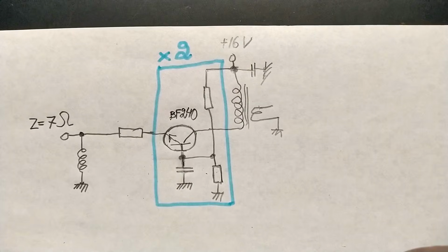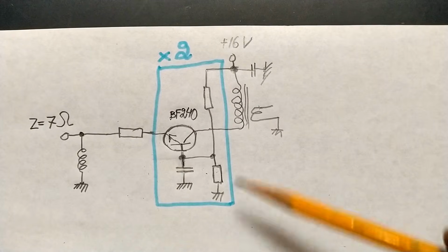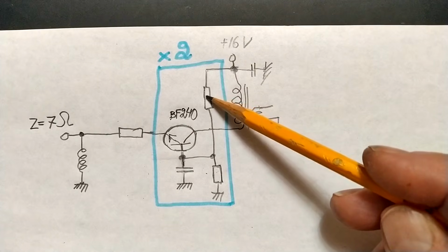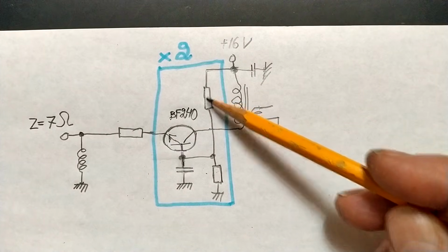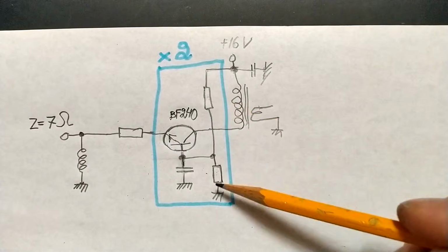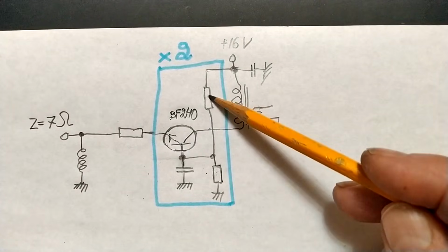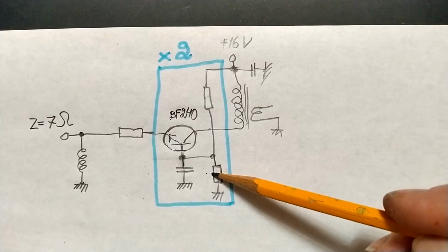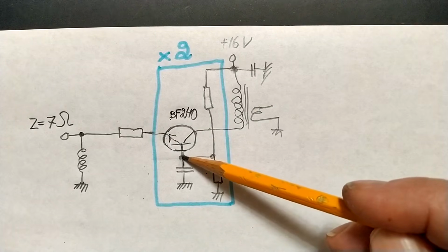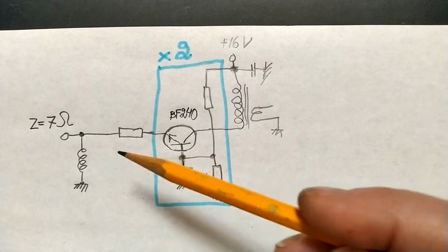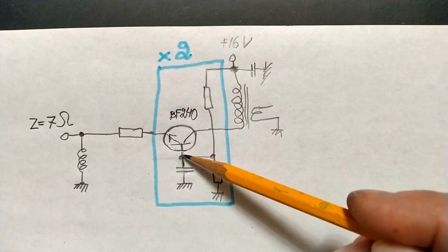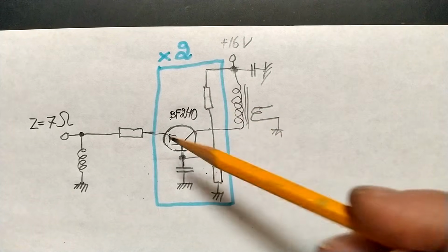This is the current amplifier, two BF240 in parallel. They have independent base supply voltages through voltage dividers with fairly low impedance, so the thermal noise should be negligible on the base, and of course independent, since there are two separate.